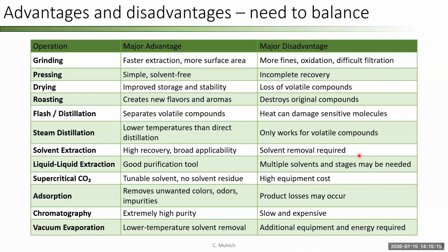So liquid extraction can be a phenomenal purification refinement, but this requires multiple solvents, multiple stages, and then the associated losses. Supercritical CO2 has amazing tunability, and it's going to leave no solvent behind.